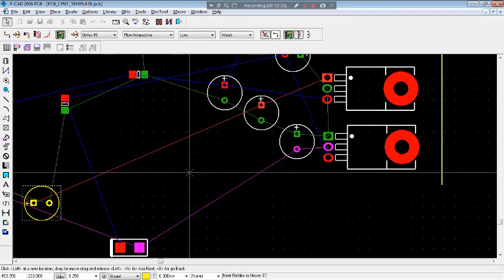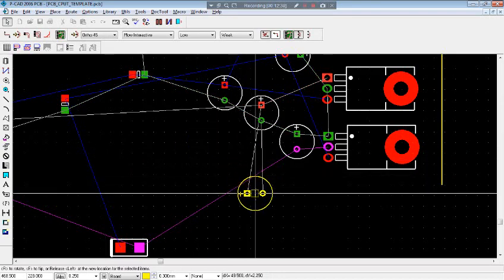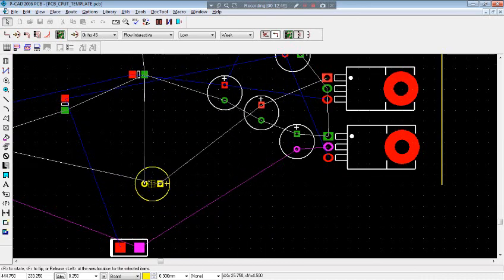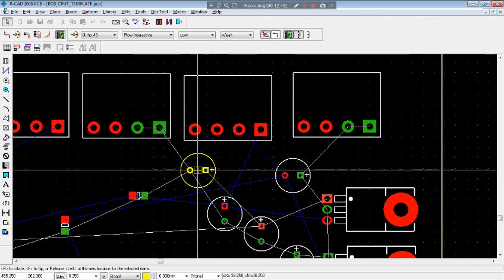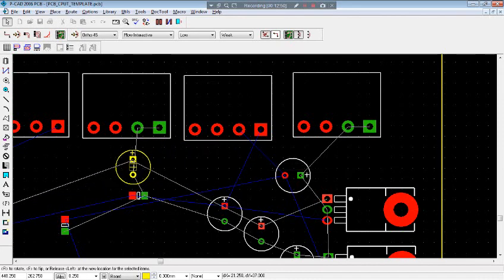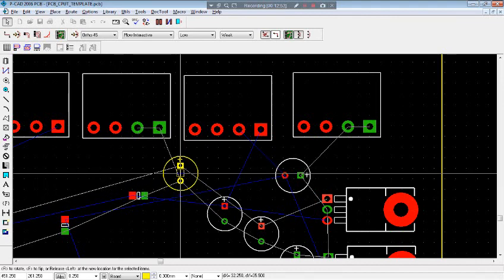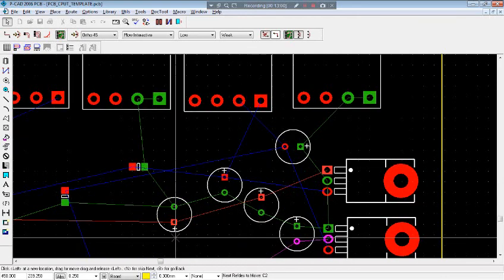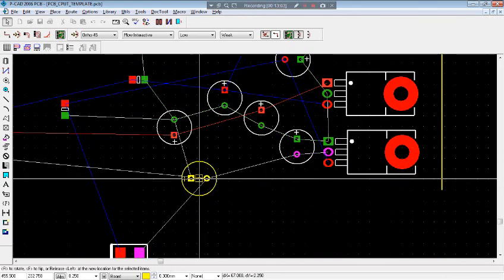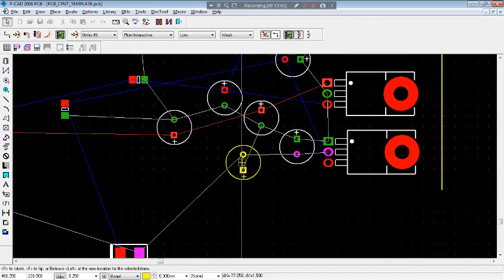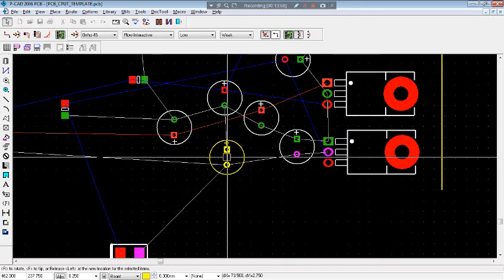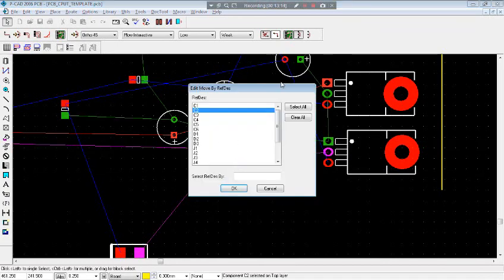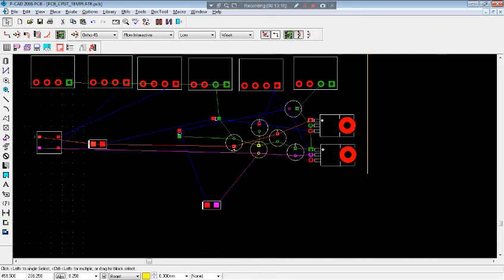Zoom in. Rotate. Rotate. See if I can find a better spot. That up there. Very tricky sometimes to decide where you actually want to leave it. For now, this seems okay. I will fix it later. Let's see. Do that, and have this like this. Try that, and it's much better. I can have it closer there, or I can have it here. Say cancel. Now all of our capacitors are placed.